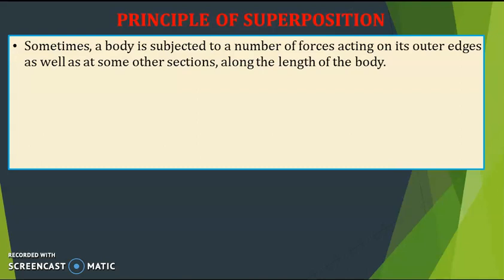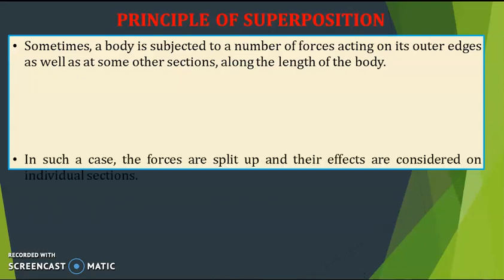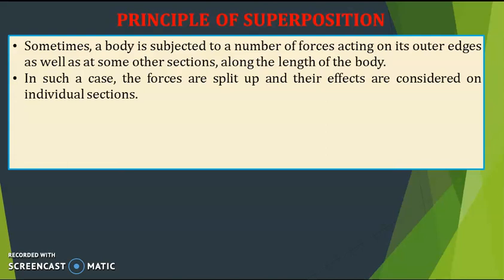See, till now you have studied when the bar is subjected to only one type of force, that is acting at the outer edge, right? But sometimes the other forces are acting at other edges also. In such a case the forces are split up and their effects are considered on individual sections. If such a case exists, you have to split up the forces and then you have to find